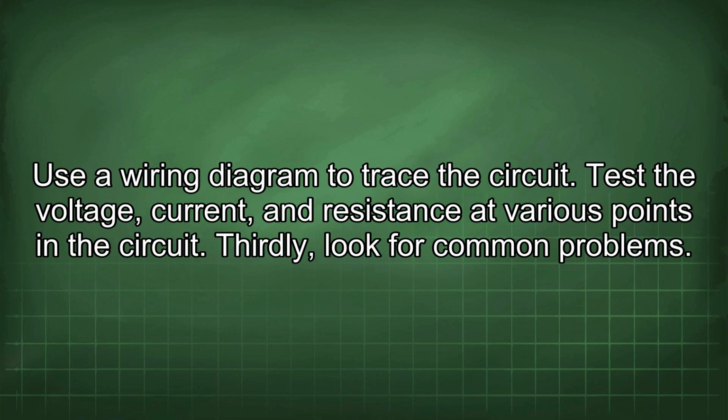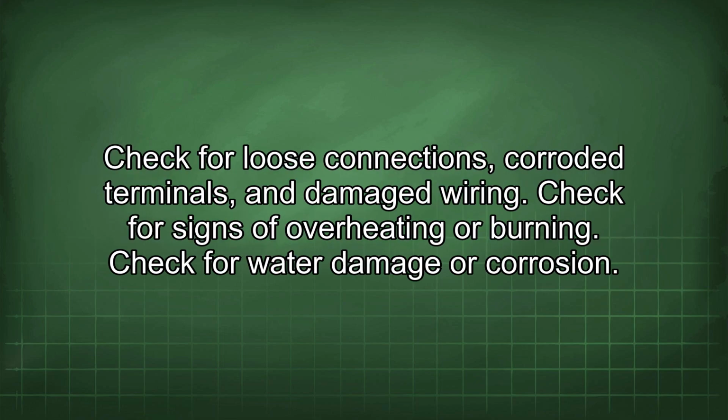Thirdly, look for common problems. Check for loose connections, corroded terminals, and damaged wiring. Check for signs of overheating or burning. Check for water damage or corrosion.